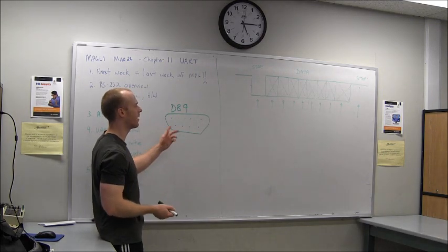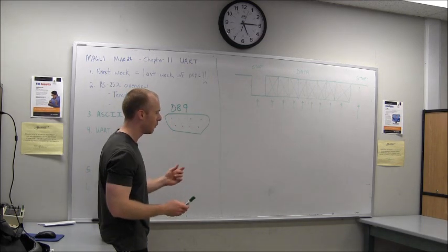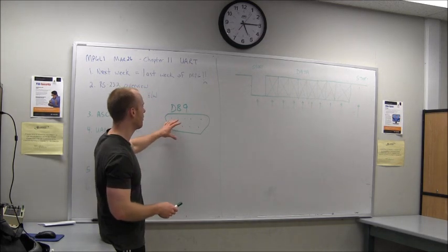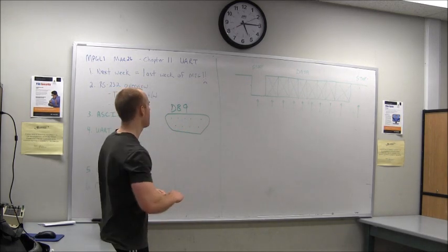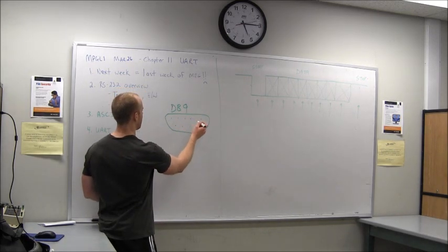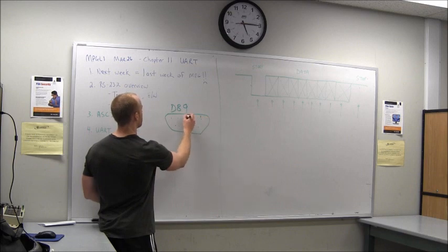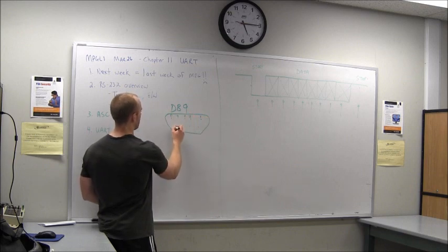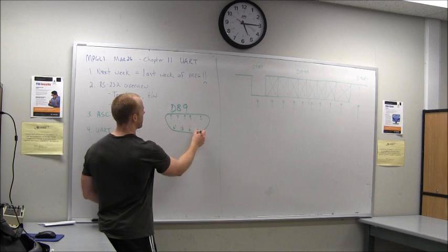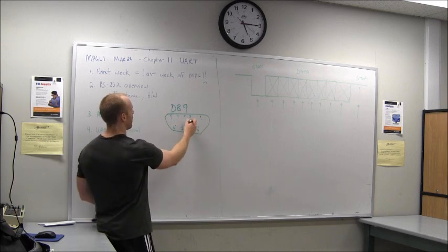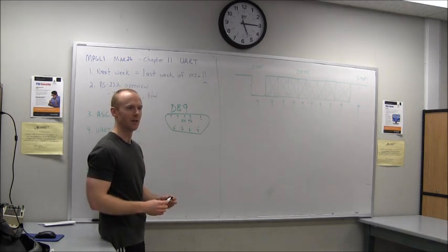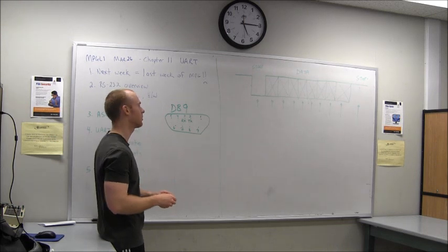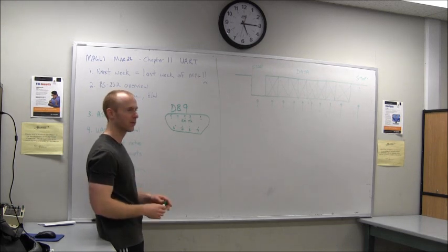A cable that connects to that is just a serial cable. Most cables are straight through, so pin 1 on here goes to pin 1 on the other side. They're usually numbered like this. There's a diagram in the notes. So 1, 2, 3, 4, 5, 6, 7, 8, 9. This is usually transmit and this is usually receive, 2 and 3. The other pins have some functionality, but you don't usually use it, but you can. There's some situations where you can use them for hardware flow control.